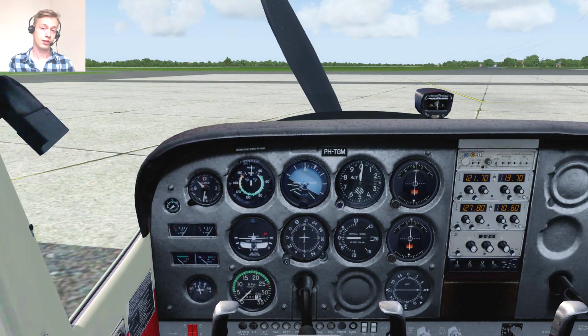Again, this may be a little bit different in your country. We are going to ask the startup at delivery, and then we'll be transferred to tower later on for taxi. But basically, what we can expect for the startup clearance is we get an active runway and a QNH, and of course we also need to take note of the latest ATIS information.